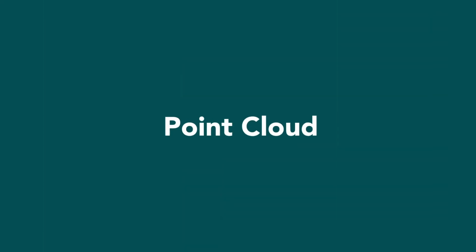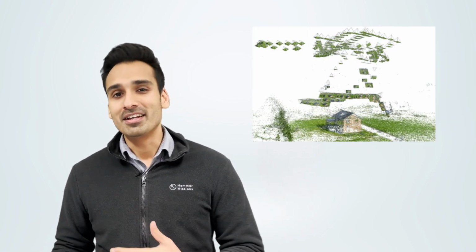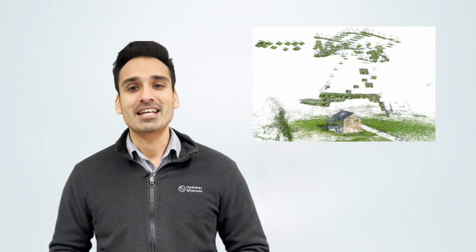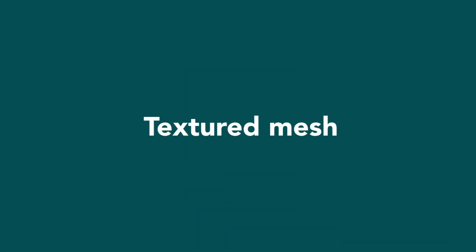Point cloud. So point cloud is essentially just a set of points. This is a set of points that can be created during the process of photogrammetry, so during the process of creating a 3D model from the images, but the term also applies when you are doing laser scanning or any kind of scanning that involves Lidar, where you also get a point cloud output at the end of it. It's just a set of points that is spatially accurate with respect to each other. Textured mesh. So textured mesh is a type of deliverable that gets created. Essentially, when you create 3D models using drone images, one of the outputs is a textured mesh.